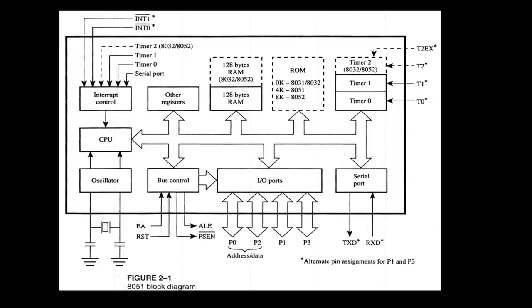While you are seeing the architecture of 8051, we can see two timers placed inside this chip itself, which are called timer 0 and timer 1. With these we can use them as timers as well as counters. The name given to the individual timers is timer 0 and timer 1. Whatever registers and other things we are going to use will be similar to the names given to those timers, so understanding the names of those timers is going to be important.